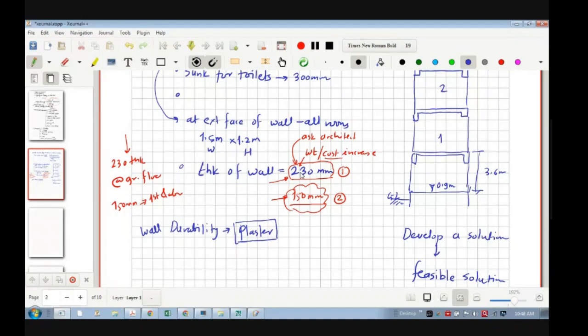If there is machinery, if there is a possibility of any explosion kind of thing, in that case the people used to have more thickness of walls. Okay, so generally for explosion areas, RCC walls are recommended, thick RCC walls, and the RCC wall may be 300 mm thick, 450 mm thick also. Wherever there is a possibility of explosion, some material is there inside the campus or room which may explode, in that case thickness of walls are more.